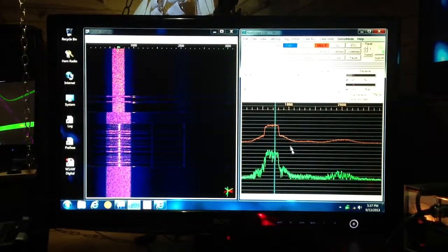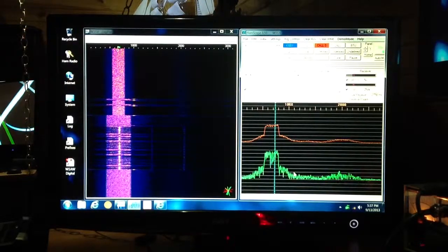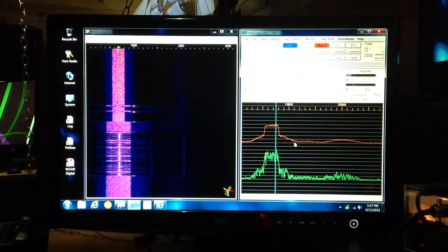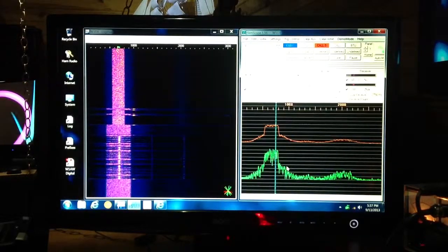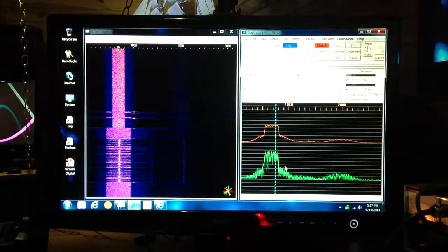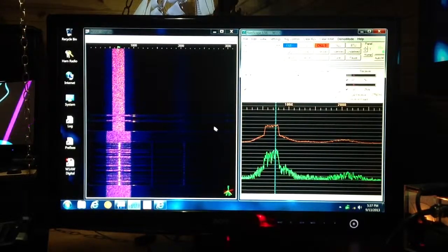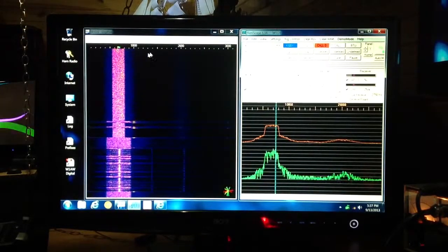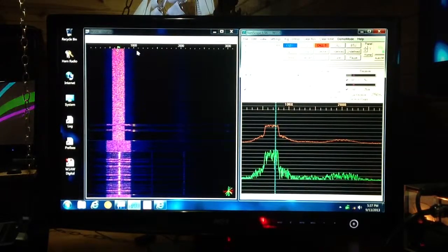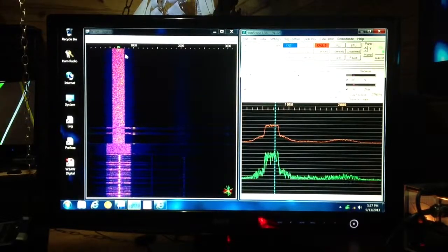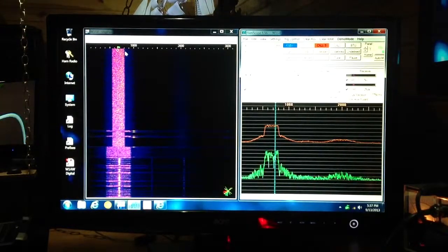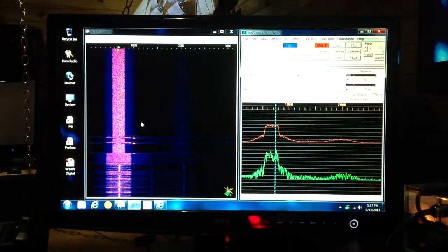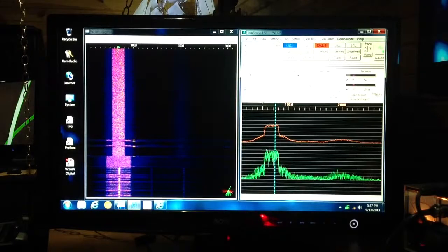You may wonder why there's an orange curve and a green curve here in HamScope. The orange curve is a slower response, so it produces more of an average over time, whereas the green is a more rapid response and produces more instantaneous results. Now this frequency again is on the horizontal axis. Amplitude is indicated by color, and then time. It also shows the third dimension of time. I think that's extremely clever. They call that a waterfall display.